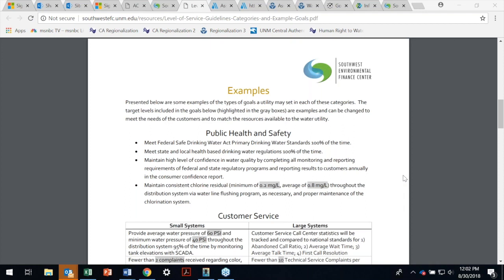And one of the things I do is our national continuing professional development training on asset management for Engineers New Zealand, so it's like the American Society of Engineers, their training. I've got a slide in there that shows an answer to this question, which is you also have to consider where the asset is in its life. This slide breaks it up into thirds. Is it in the first third, the middle third, or the last third of its life? For a lot of assets, pipes particularly, if you're doing maintenance in the first third of the life, it'll be because somebody's hit it with an excavator or it wasn't built properly to start with. It's still in the defect liability period.